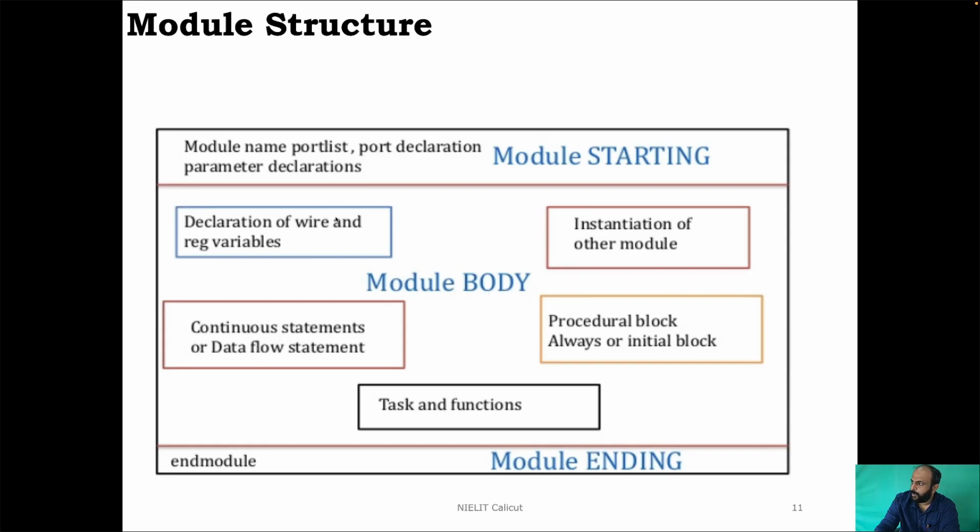Then if the module contains only one piece of hardware logic, it's fine. Otherwise, if it's a combination of multiple hardware, you will have to instantiate other modules. It is illegal to nest a module, so you can't write a module within another module. You can only instantiate it. I will explain the process of instantiation.